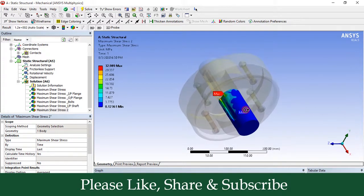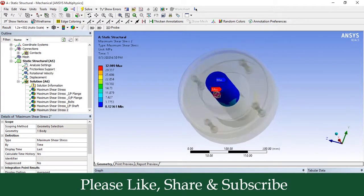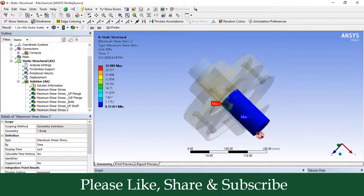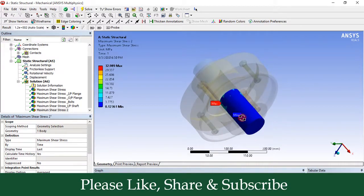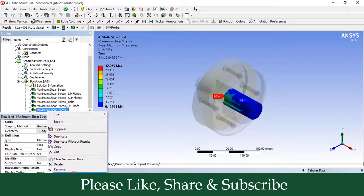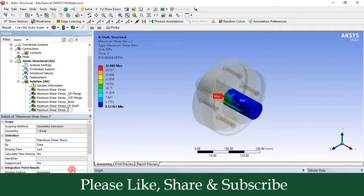So this is the point of minimum stress. Okay, so minimum shear stress is at this point. So this all blue color region shows that this is the area or the region of minimum shear stress and the maximum at the slot of keyway. So let us rename this parameter. So this is for output shaft.